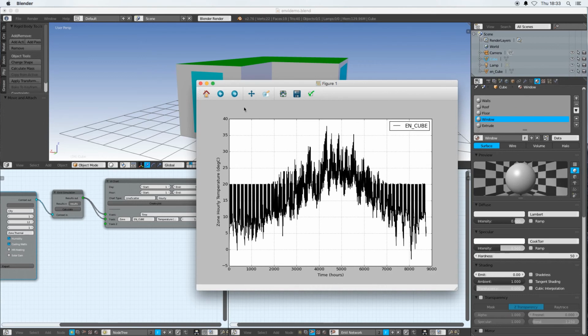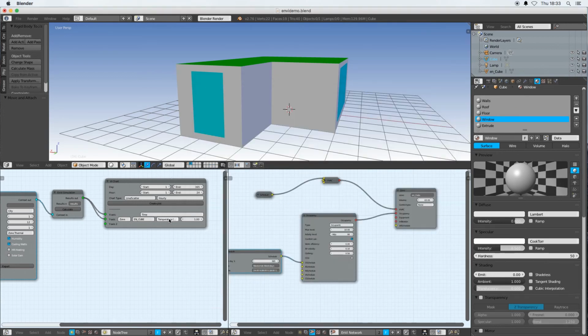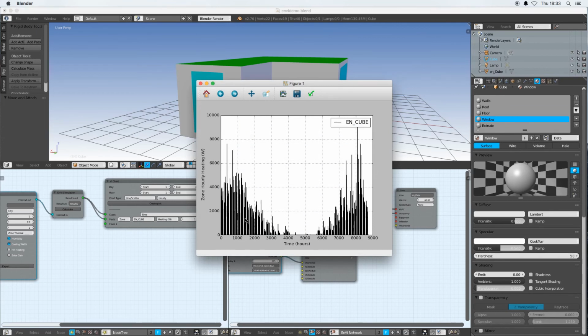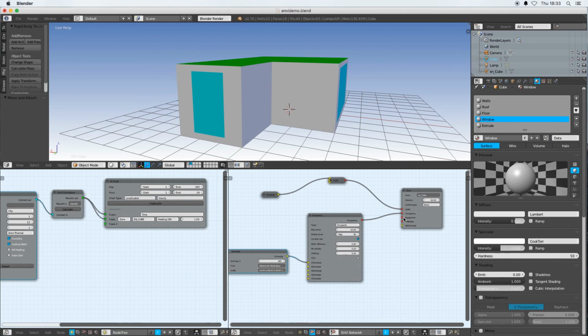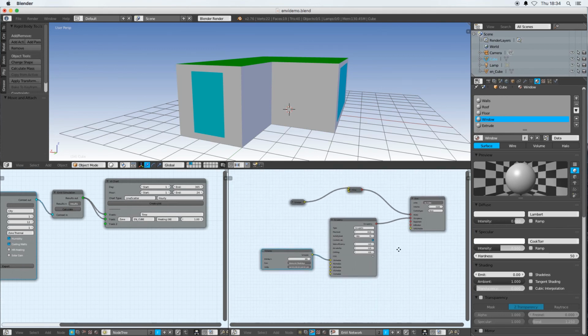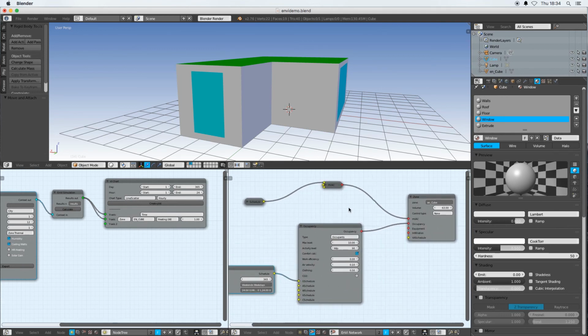And we should then see also an impact on, for example, the heating consumption required in that space. So we can see when the heating is off, and these levels now, when people are in the building, are much lower than they were for the initial simulation. So that's pretty much it. We can set constant or scheduled levels of internal equipment heating gains, and we can also specify a simple ventilation infiltration coming from outside into the zone as well. But for the basics of zone specification, I think that's all I need to cover.